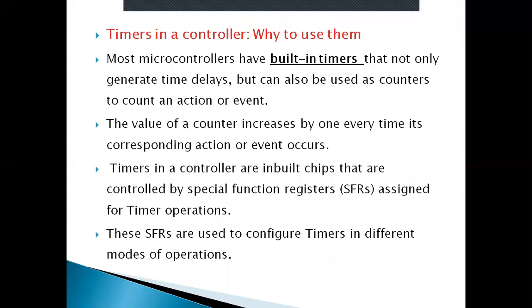Why do we need timers in the microcontrollers? Basically, the timers are required to generate delays, and for generating delays, we have two ways. One is using software, another one is using hardware, the timers. Using software, if you want to generate time delays, then you need to write loops, for loops and all those things, and you can generate the delay. And if you want to generate it using the timers, you can do it so again through programming. But when you generate a time delay using timers, it will be more precise compared to the delay generated using software.